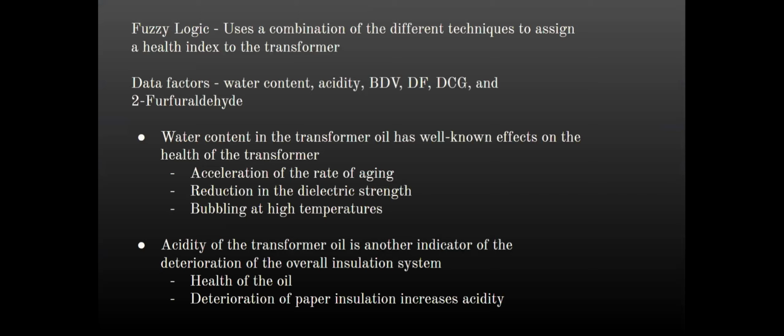And I'll pass it over to Joel. All right, thanks, Jesse. So I'm going to talk about fuzzy logic, and fuzzy logic uses a combination of the different techniques and assigns a health index to the transformer. The data factors that go into that are water content, acidity, breakdown voltage, dissipation factor, dissolved combustible gases, and formaldehyde.